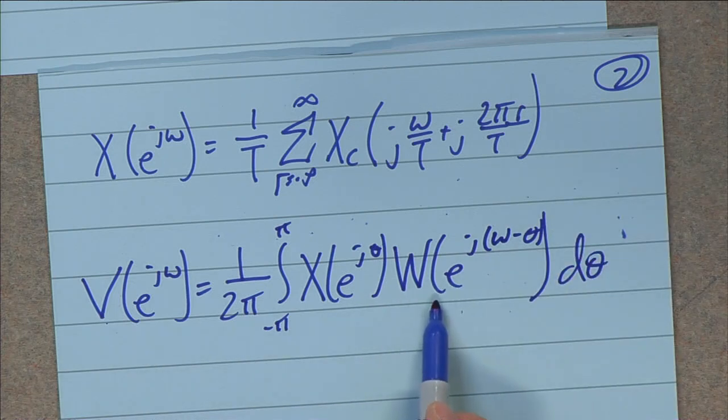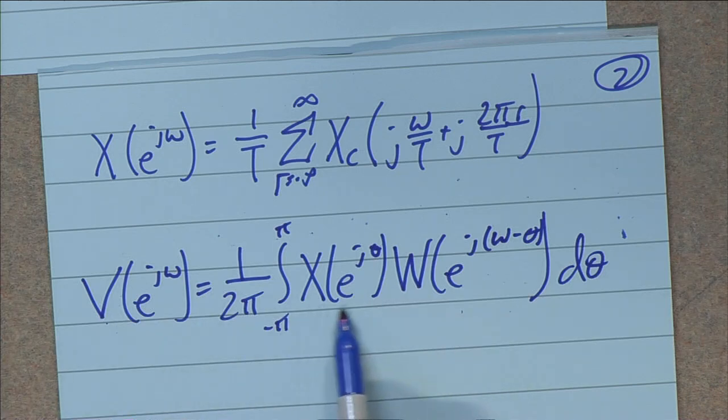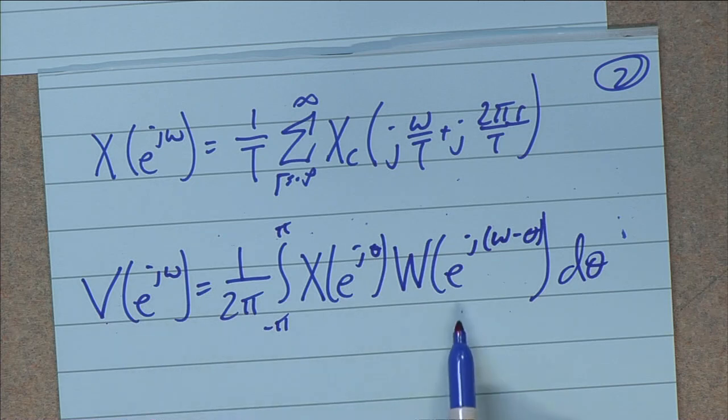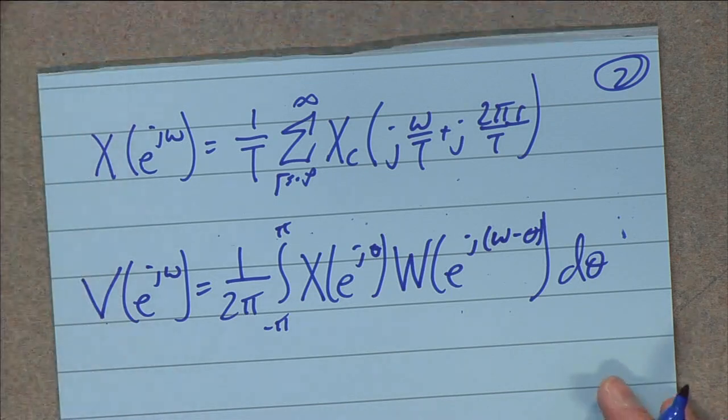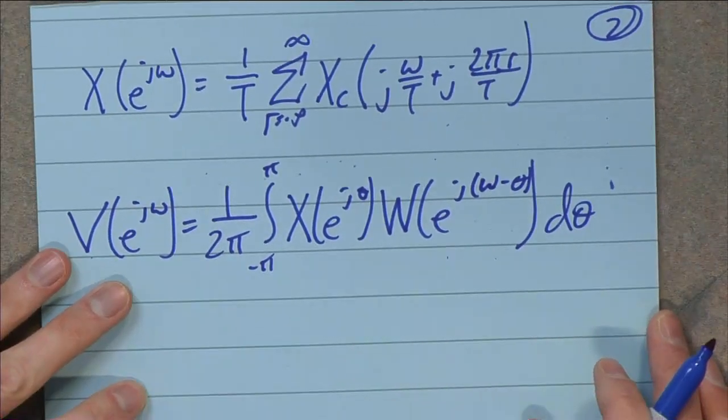The convolution with this is going to basically affect the output spectrum. When you convolve this, the sharp peaks and discontinuities in the spectrum will go away. Now if you're looking for sharp peaks and you're trying to resolve very closely spaced signals, because those have information for you, then that can have an effect and it can cause a problem. And we're going to dig into that a little bit today.